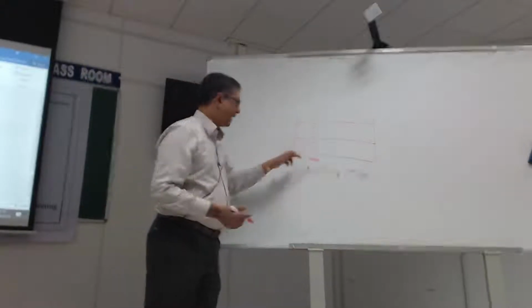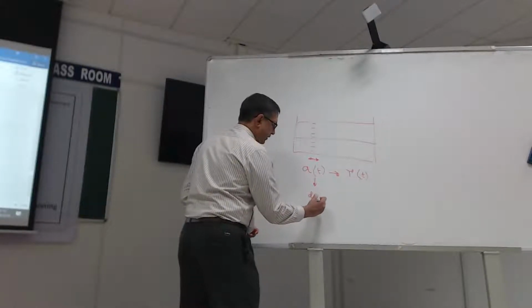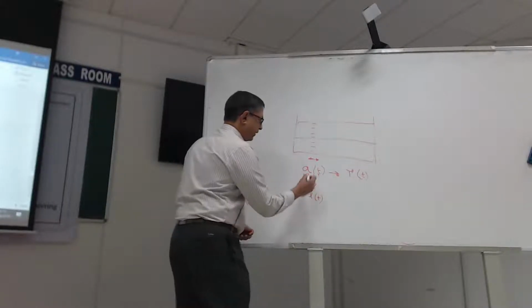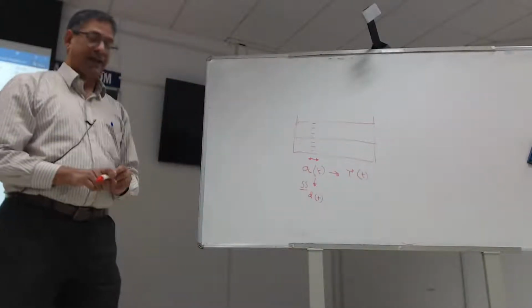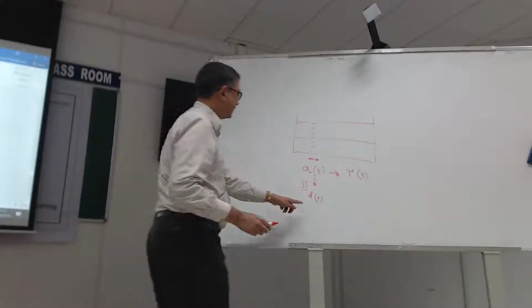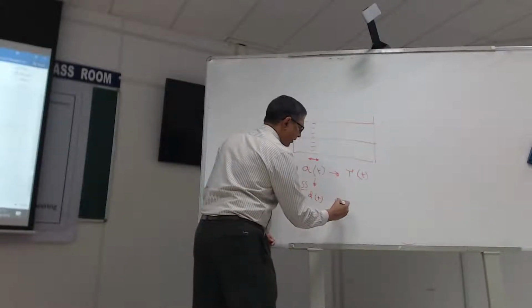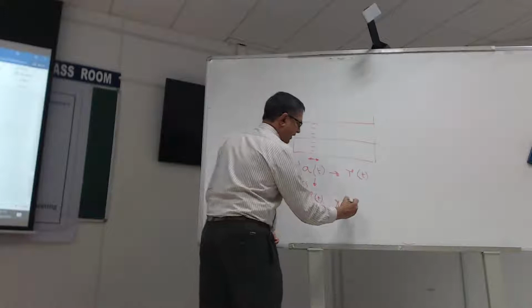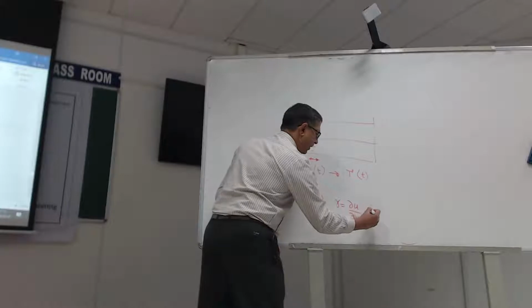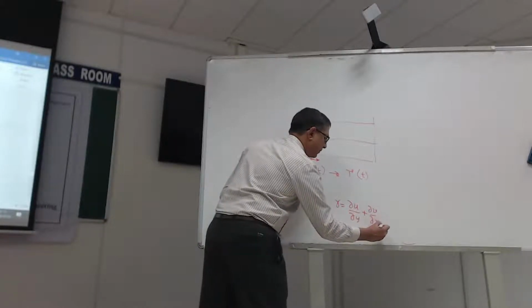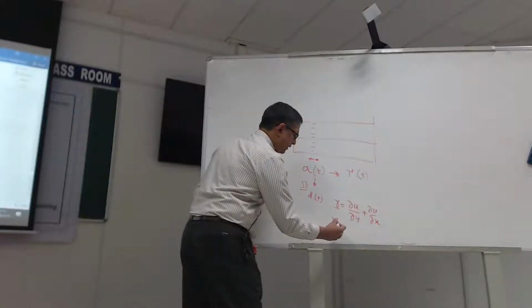Because I am measuring acceleration, I can double integrate that to get my displacement, with some careful application of the boundary conditions. You should be able to get displacements. If I know all the displacements, then the strain gamma is basically the difference in displacement over the layer thickness. So we should be able to work out the strain as well, and I'll get the strain history.